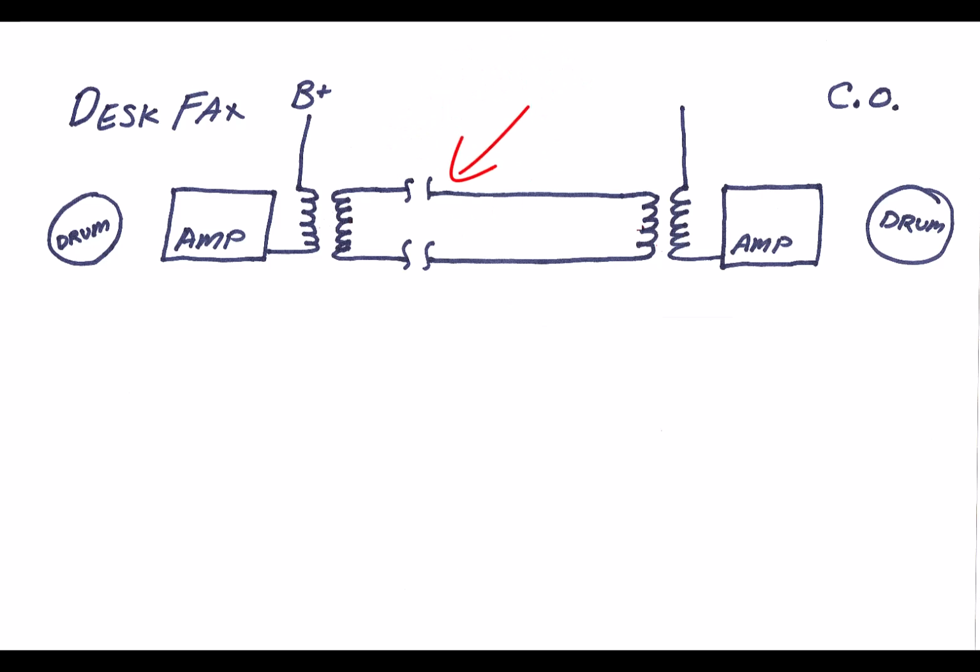To this subscriber loop, on the transformer winding that's attached to the loop, meaning on the central office side, not the amplifier side, let's put a contact to the winding at its impedance midpoint. A center tap, if you will. And let's do this on both ends. And this circuit also requires a return path. It's just going to use the return ground for the 0-volt connection, and since the AC mains are not grounded, or even polarized for that matter, the ground was most likely just created locally.